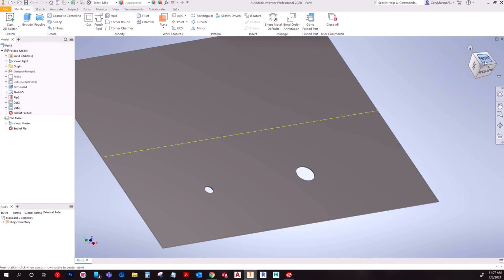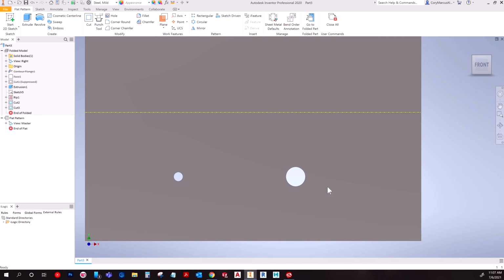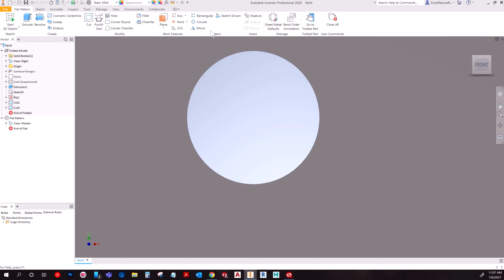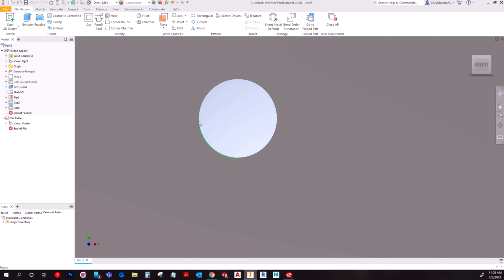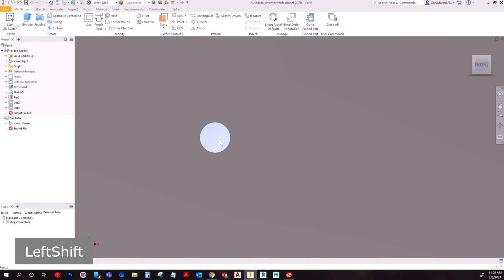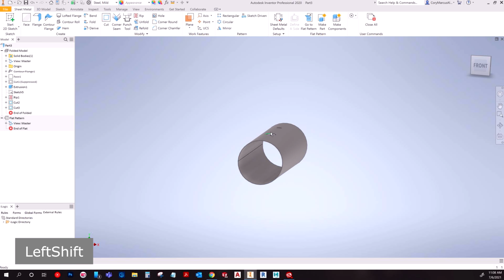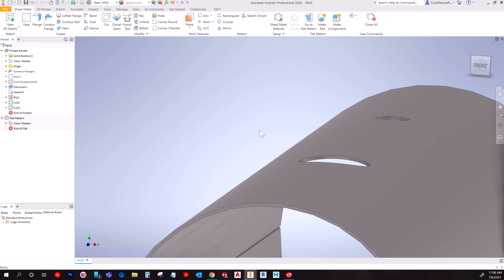And what I found was I would model these in and make sure to use arc length and get them located properly, and it just never lined up right. Never. It's because you basically need to use cut normal. If you notice, this is a perfect circle, and so is this one. You wouldn't expect that, but they are. Whenever you're making something like this flat, nobody can cut a really oblique, broken hole. They need a perfect circle, something easy to cut out.